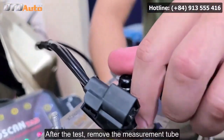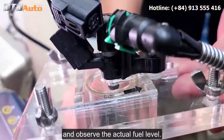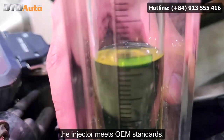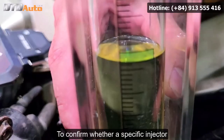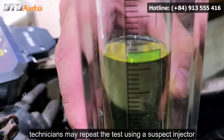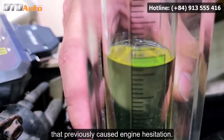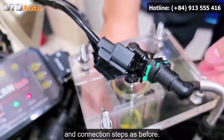After the test, remove the measurement tube and observe the actual fuel level. If it aligns with the green marking, the injector meets OEM standards. To confirm whether a specific injector is the root cause of poor engine performance, technicians may repeat the test using a suspect injector that previously caused engine hesitation. Follow the same installation and connection steps as before.